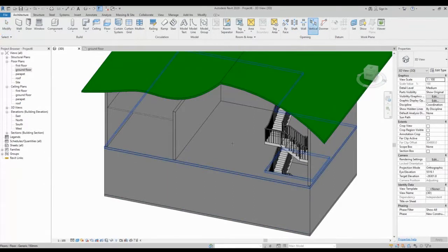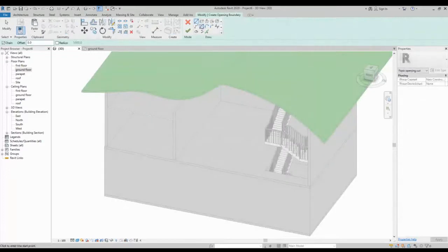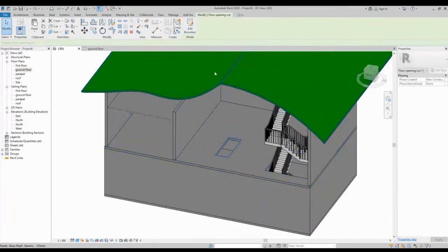Also, we have vertical. Vertical is basically the same idea, but instead of face, this is creating a vertical opening. I'll show you the difference here. In by face, it will not extrude vertically. It will extrude aligned to the face that you have. But when you go to the vertical one, it will extend vertically, so the edges will be vertical.